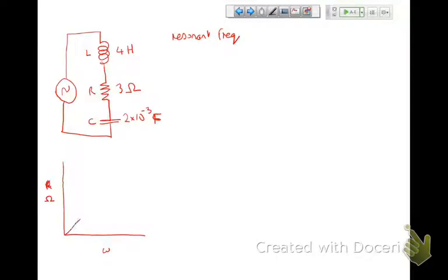And if the inductor is killing you at high frequencies and the capacitor is killing you at low frequencies, and the resistor is just constant, what we get is a situation where when I add these together, I get something that looks like that. I get my Z is that, the total effect. And as you see here, there's a minimum Z, Z min.